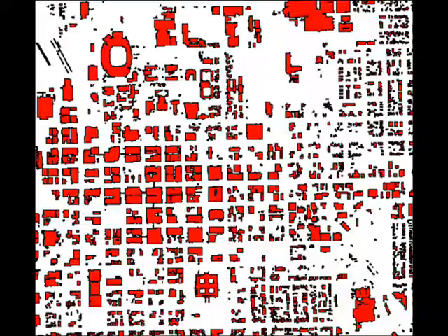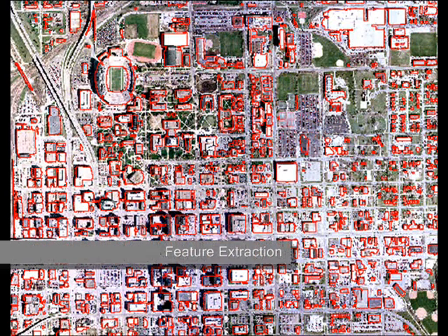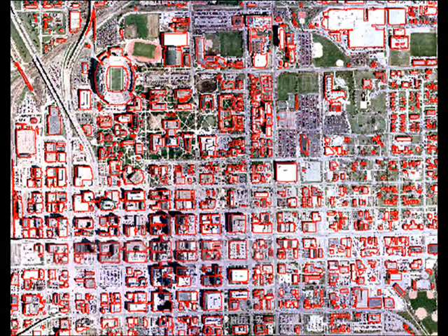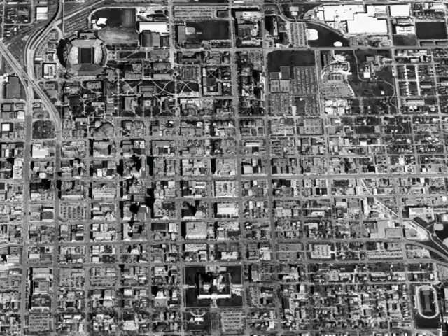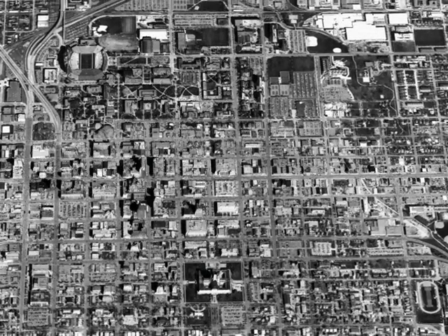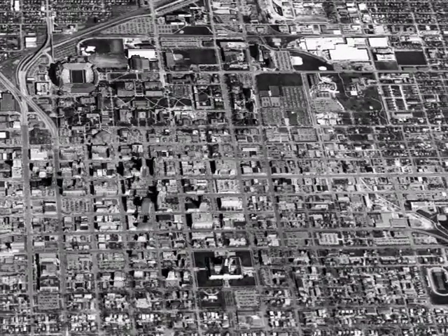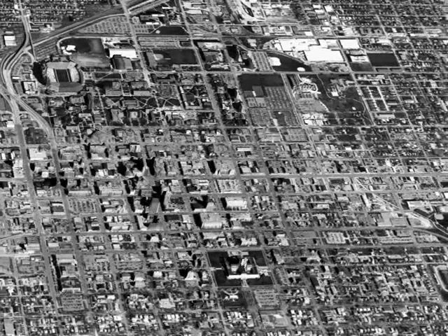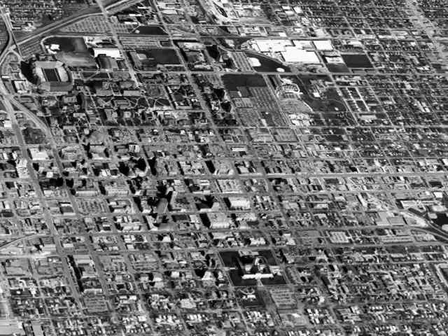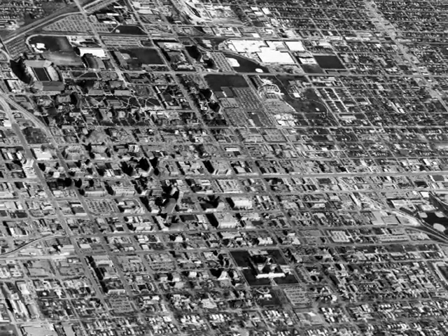For example, using LIDAR data, building footprints can be delineated by successive classification and eventually extracted as vector features. This technique is not perfect and requires additional processing in most cases, but is generally less labor-intensive than many traditional methods, such as digitizing from orthorectified imagery. These extracted features can also be recombined with bare earth terrain and draped imagery, producing a very realistic three-dimensional representation. Among other fields, three-dimensional city models are useful for emergency management.